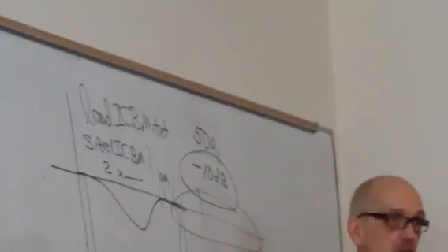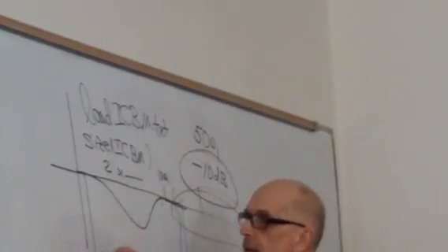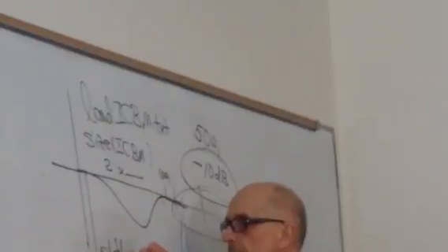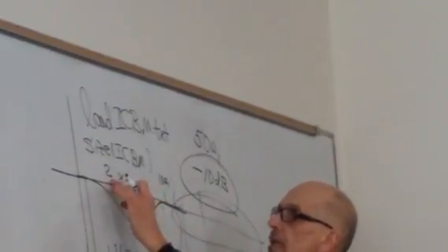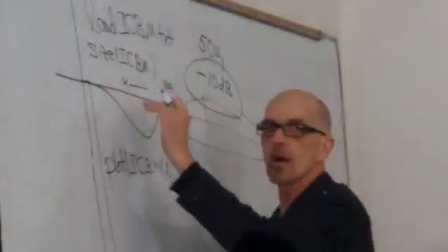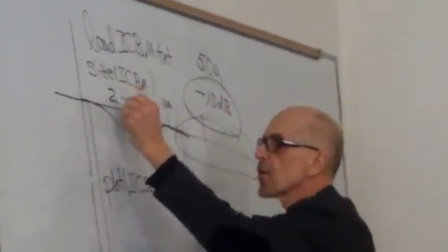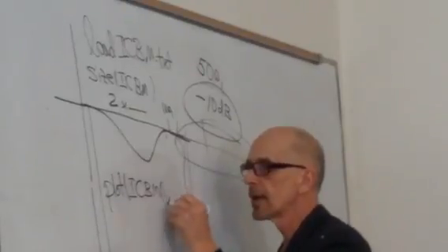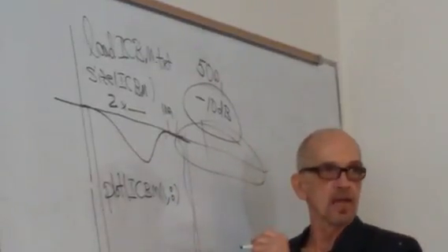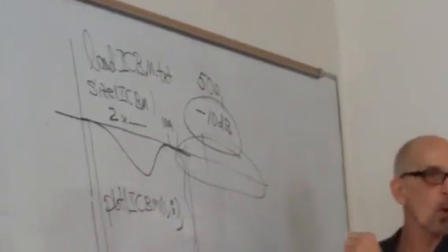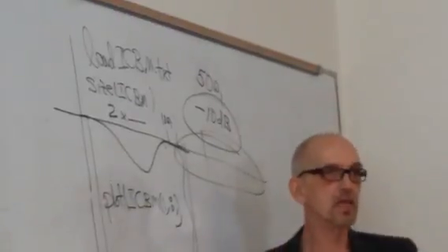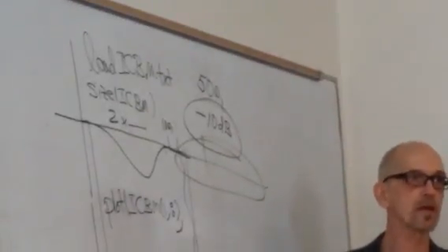So if you wanted to plot that, just to make sure you got it entered into your workspace, you'd say plot ICBM, it is 2 by, so you'd say 1, comma, colon. That's the x coordinate or the time coordinate, comma, ICBM 2, comma, colon. And you should get that plot that's given there, just to verify that you're working with the right data.